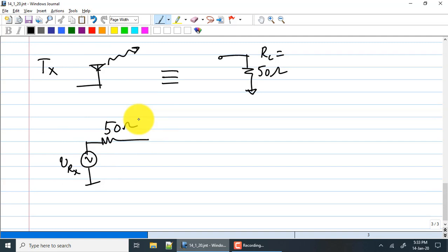It may be several tens of millimeters away from the IC on the board, let us say on the printed circuit board. Which means, as far as the electrical equivalent circuit goes, you now have a transmission line of some certain length between the antenna and your circuit.